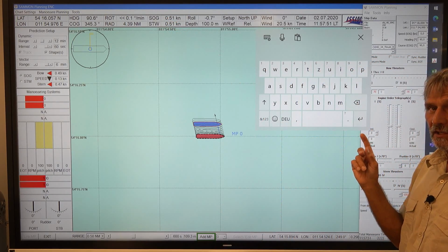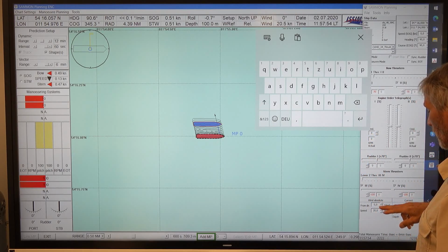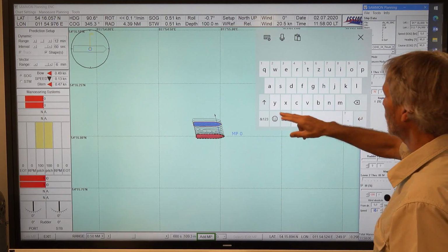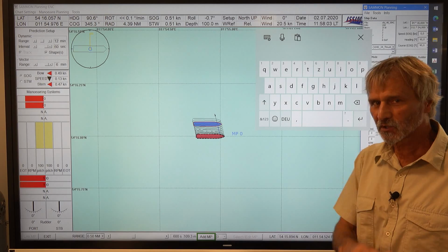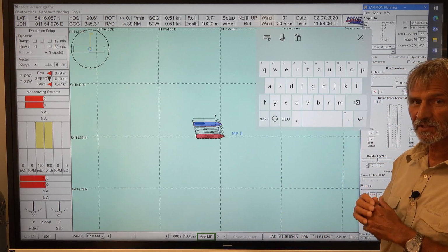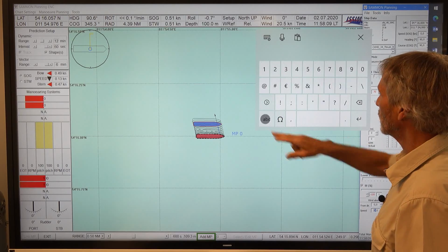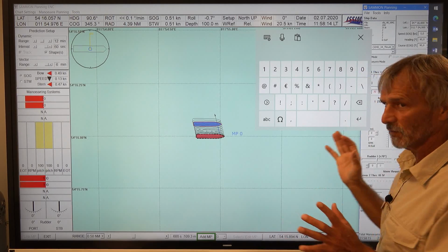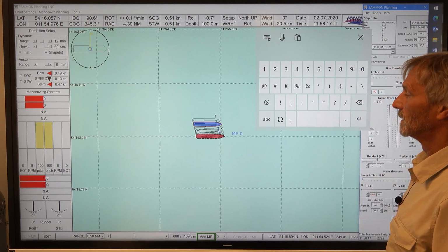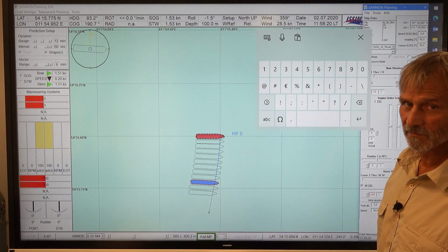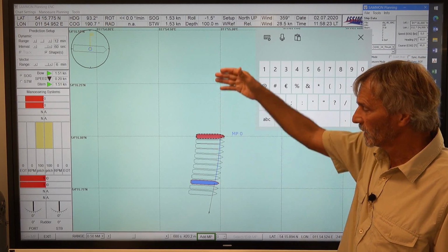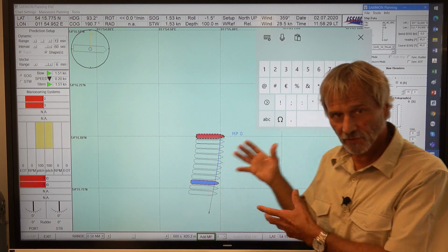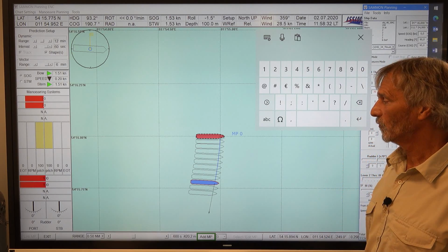If we increase the wind speed now up to 30 knots, we need again our small tableau. I could do it also on my tiny laptop computer, which goes much faster, but for reasons of the demonstration, I will do it with this tiny panel. So we set it now to 30 knots of wind. And the question will be, can we stand 30 knots of wind? Enter. Then we see, no, we don't. So clearly with 30 knots of wind, we go here with this drifting speed of 1.5 knots. We will drift with the wind with 30 knots of wind.